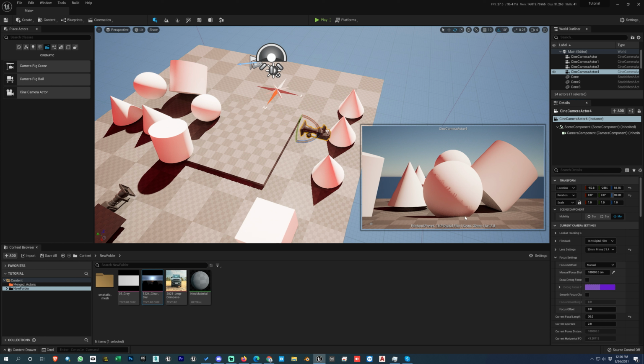And then this is focus setting, which is very helpful, so I'm going to explain this. Suppose we want this sphere to be visible very clearly, and behind this sphere there should be depth of field in your scene. You can just click here and select that sphere in the scene.